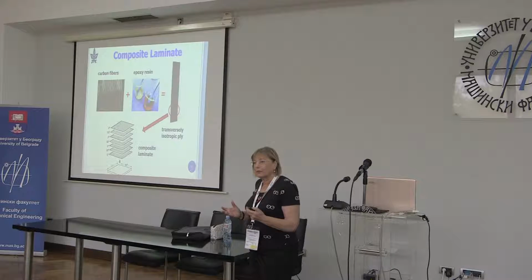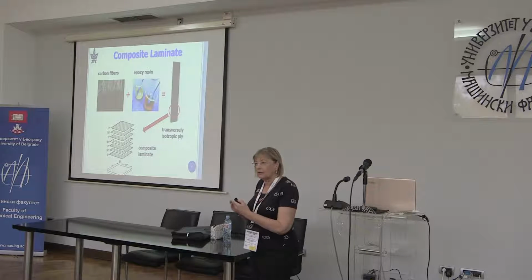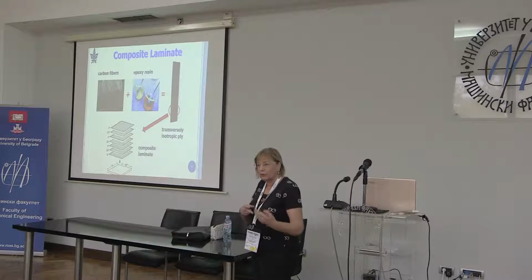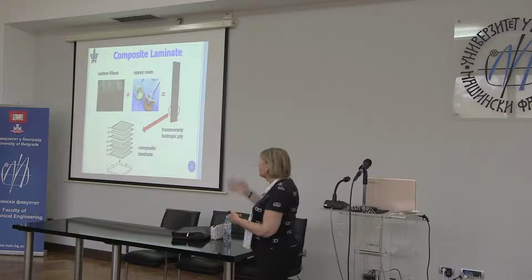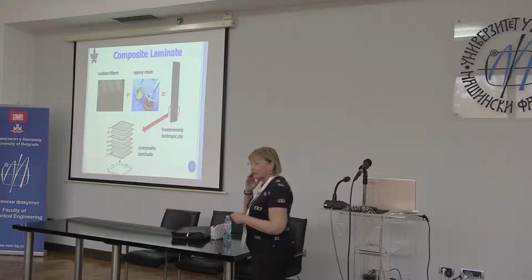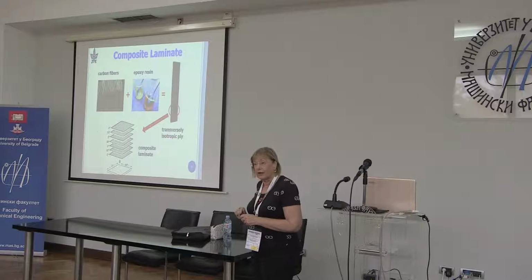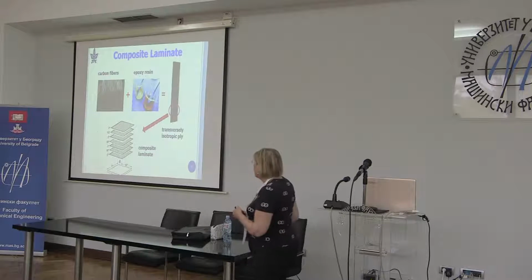Now, isotropic materials have 2 independent mechanical properties, let's say E and nu, or mu and nu, because if we have E, mu is dependent on E and nu. If you have transversely isotropic materials, it has 5 independent mechanical properties that describe it.